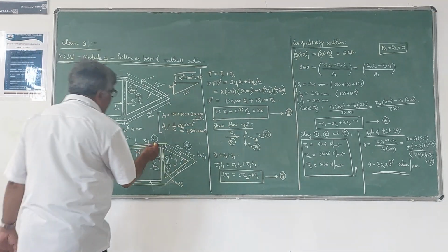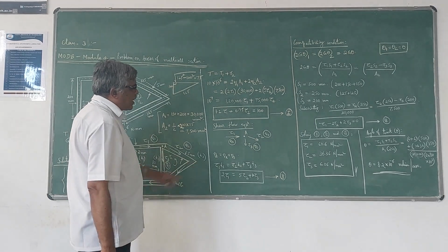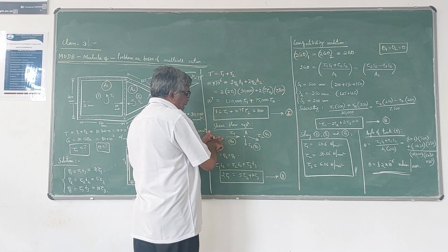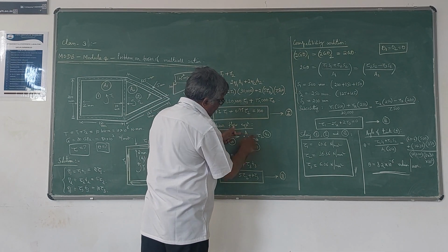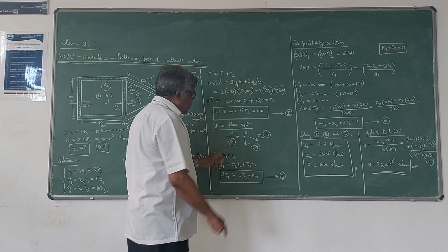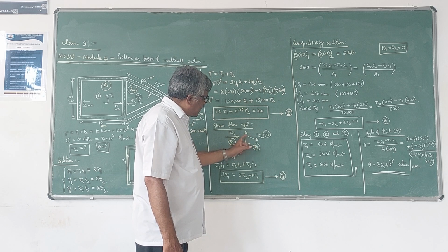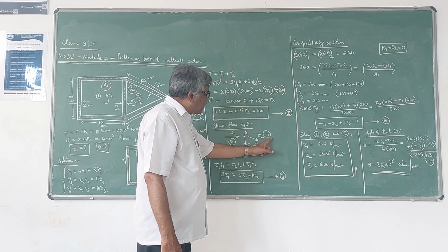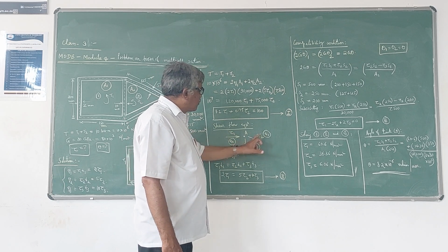Now if you take the point A here at the junction, you can see that τ1 is acting like this. I have assumed like this, τ2 I have taken like this, τ3 like this. That means τ1, which is the shear stress, and q1, which is the shear flow, is split into two parts, q2 and q3. That means the equation is q1 is equal to q2 plus q3.